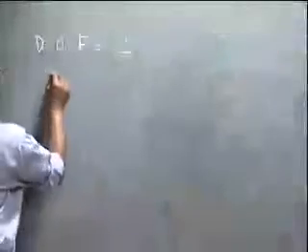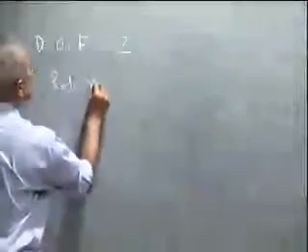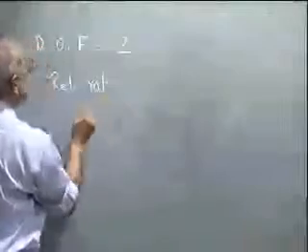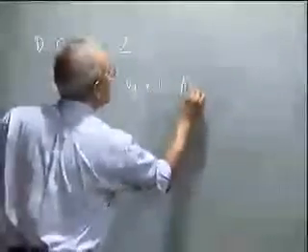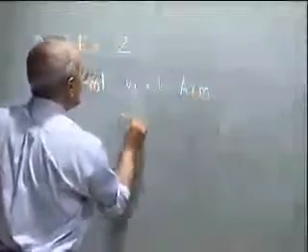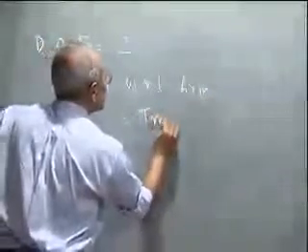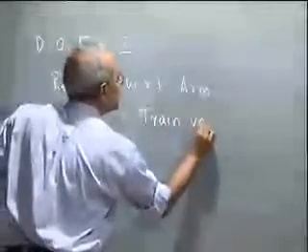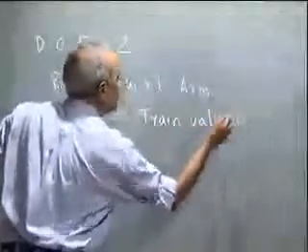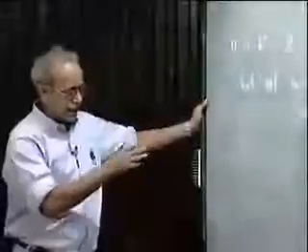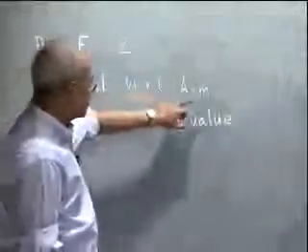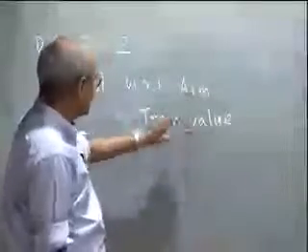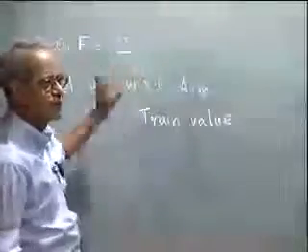To analyze this epicyclic gear chain, the only thing to note is that the relative rotation of the gears with respect to the arm is equal to what we call the train value. That is, as we get normally in a simple gear train or compound gear train using the number of teeth. So it is the relative rotation with respect to the arm that is given by the train value, not the absolute rotation ratio of two gears.